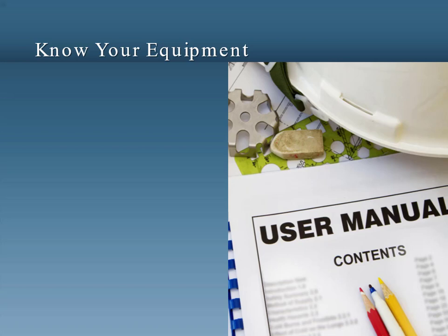Before using any type of aerial lift, it's very important to become familiar with the equipment. Take the time to review the information on accident prevention signs that are required to be posted on the equipment. Look for warnings, cautions, and restrictions. Following these instructions will help you operate the equipment safely.